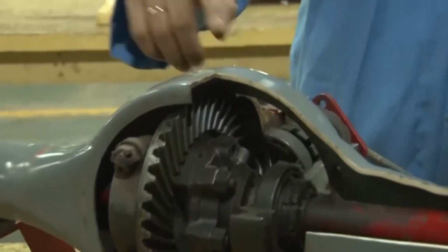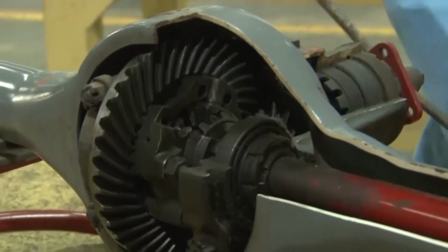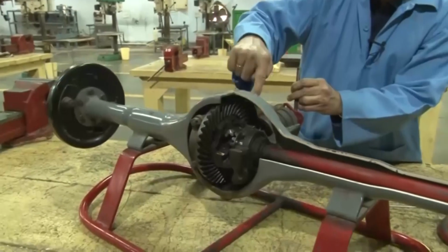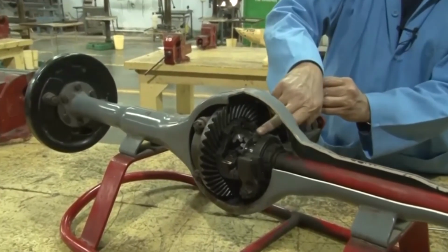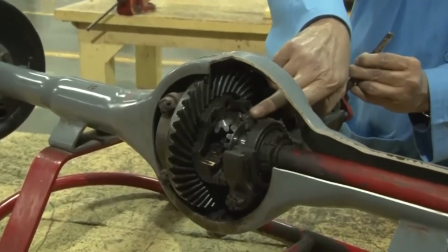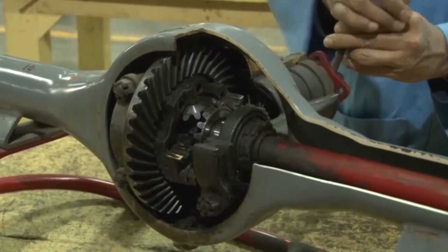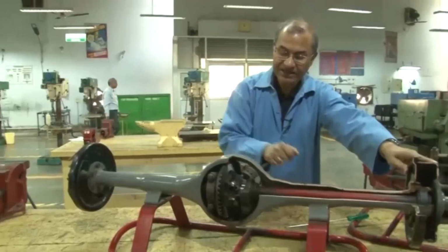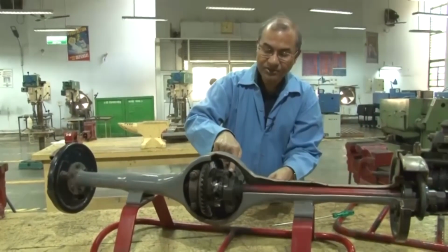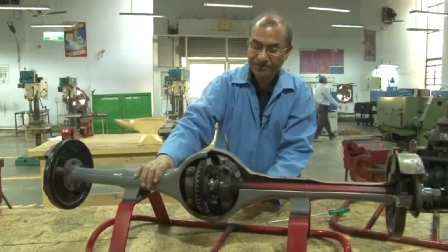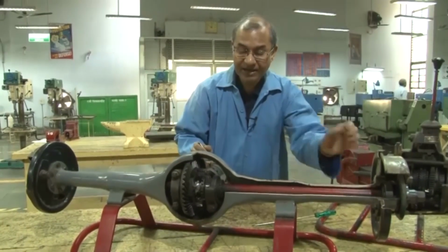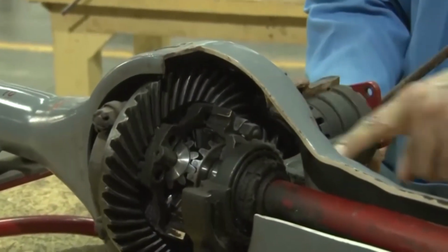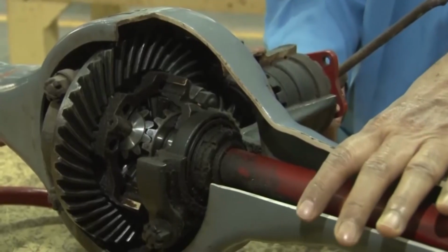This is the differential mechanism, that is why it is called the differential, because there is a difference in the speed between the two wheels, and this is done by the planetary wheels, and planetary wheels are connected to the shaft of the other wheel. So, basically once again this spiral gear of the input shaft is connected to the spiral gear of the output shaft, and then in its turn that spiral gear with the help of the planetary gear is connected to the other wheel.